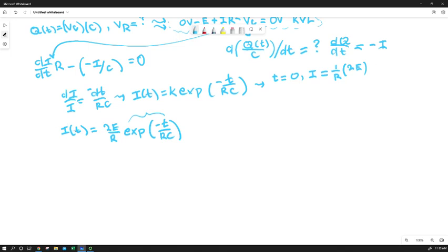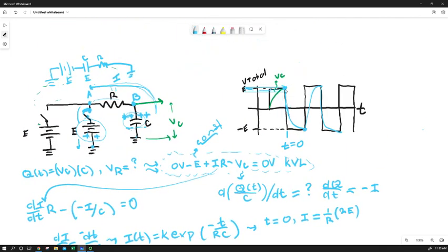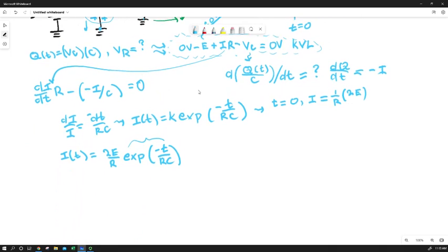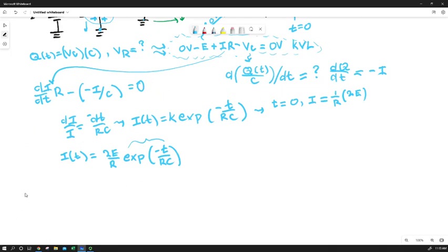So we know that we will eventually reach a point where basically the capacitor becomes oppositely charged, it opposes the source, and then current stops. So that's the behavior we would expect. Now it's great that we have an expression again for current that's flowing through the capacitor during this time here, but what we're going to measure in our circuit is voltage. So we still need to go that extra mile and create a time-dependent expression for the voltage drop over the capacitor, since that's what we're going to measure in our circuit.